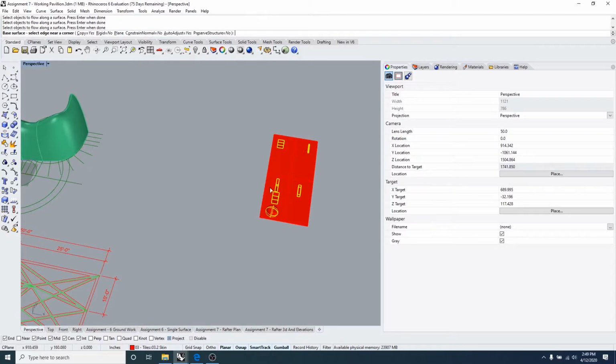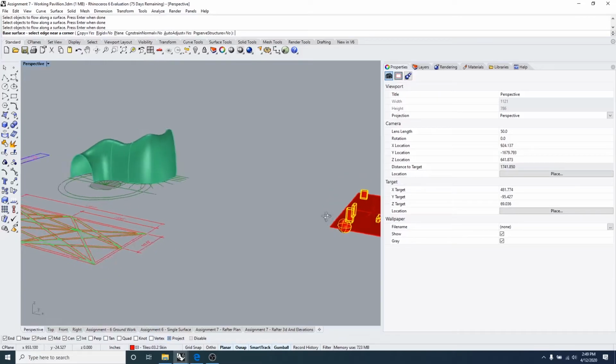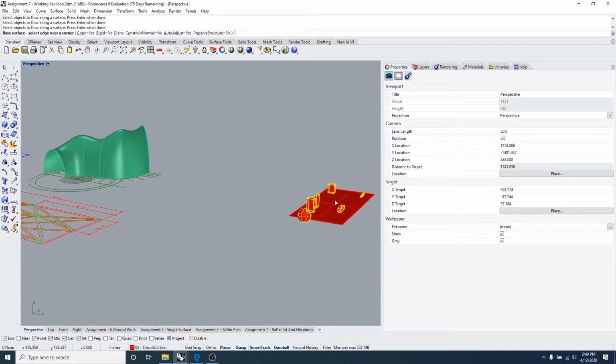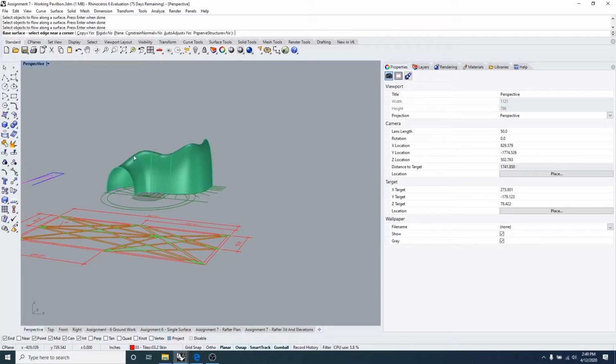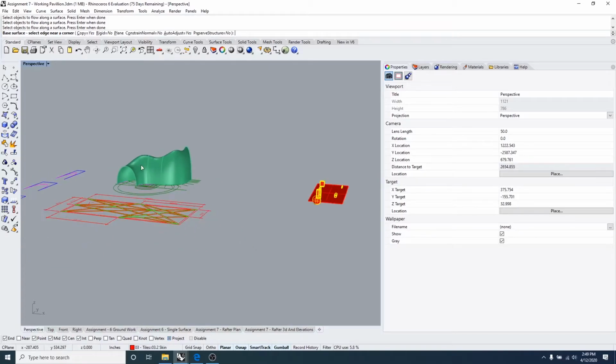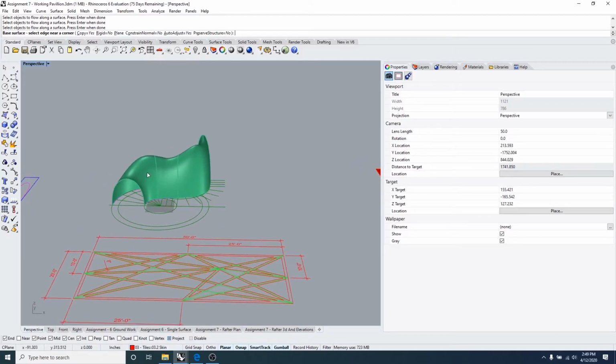Because we have a plane already established here, we're not going to use that plane. The constrain normal is going to constrain the direction of these objects. If we enable that, they're always going to be pointing up pretty much, depending on your normal direction. We know that our direction is always going to be pointing up in this instance.